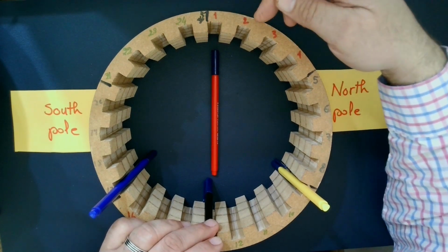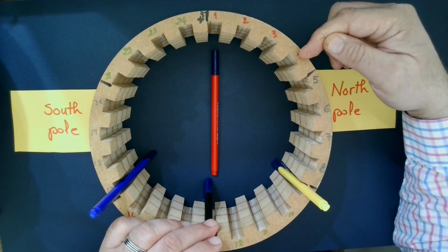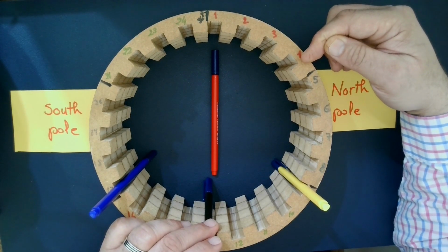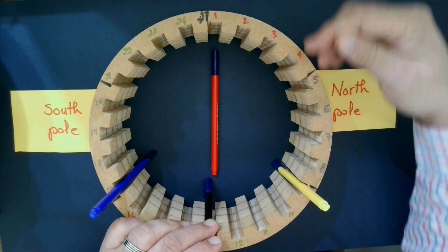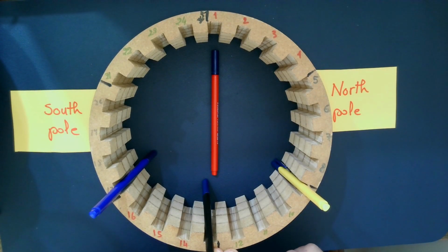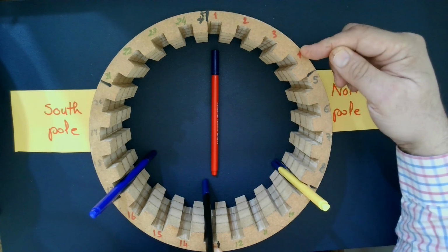1, 2, 3, 4. 4 multiplied by 15 will be 60 degrees. 60 degrees will be the spread angle, as explained to you, the spread angle per phase. So how many slots per pole per phase? We have 12 slots per pole. We have 3 phases, so that one will be 4 slots per pole per phase.